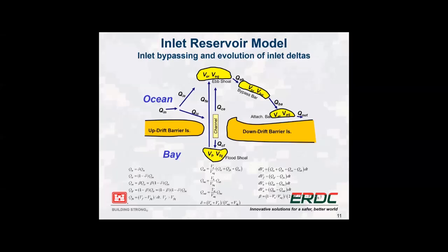If it's stabilized, you usually can estimate the difference of shoal volumes in scale. Usually the ebb shoal is the largest element, so you can use your map to estimate the proportional change from the ebb shoal to the bar and set up an initial guess of the other bypass elements.